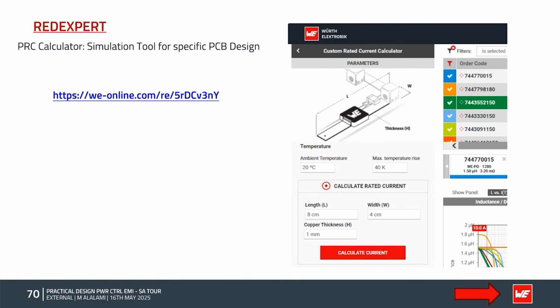If you're happy to accept 50 degrees temperature rise instead of 40, you'll have higher rated current naturally. If you only want 20 degrees temperature rise, you'll have lower, custom rated current, I should say. You're customizing that value based on your requirements.